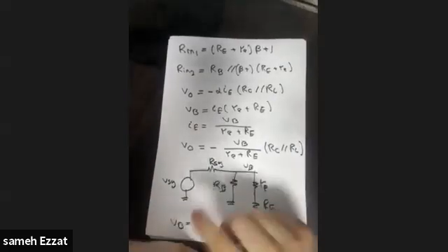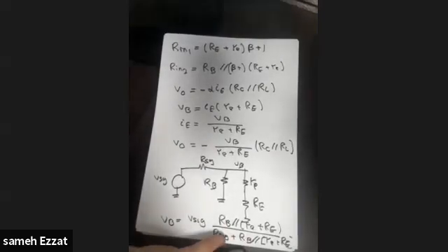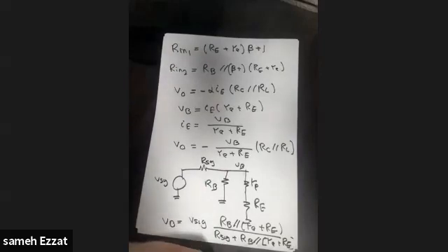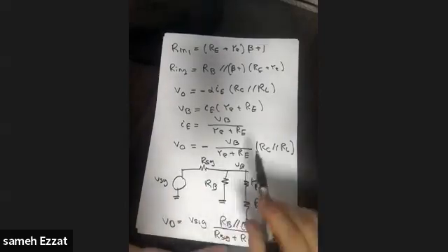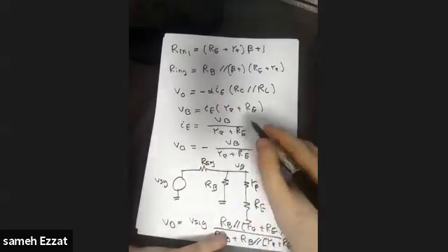Now let's come to the final question, which is actually my first point. When we start solving this equation, I told you we don't need to make any DC analysis. Here you have to wait a bit and ask me why we don't need to make any DC analysis. As we can see here, the gain, for example, is a function of re. So we need to calculate re. What about re? I think I mentioned it in the beginning.